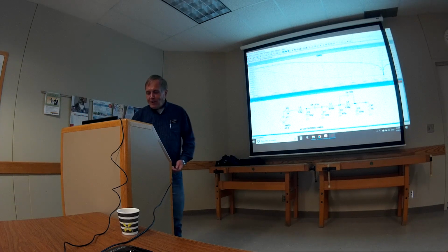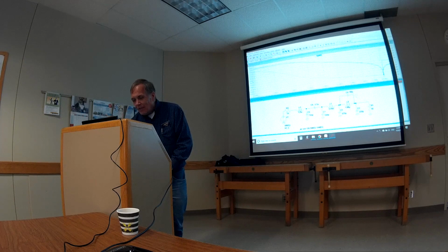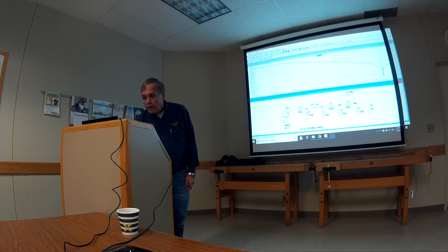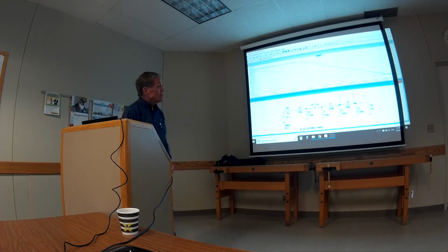I want to just show you quickly what it would look like without that capacitor in there. So, you go up to the little scissors up there, by the way. That's how you get rid of a component. Click on the scissors and you come down here and you say, snip. Okay, now what's this thing going to look like? So you poke the running man. What does it look like?